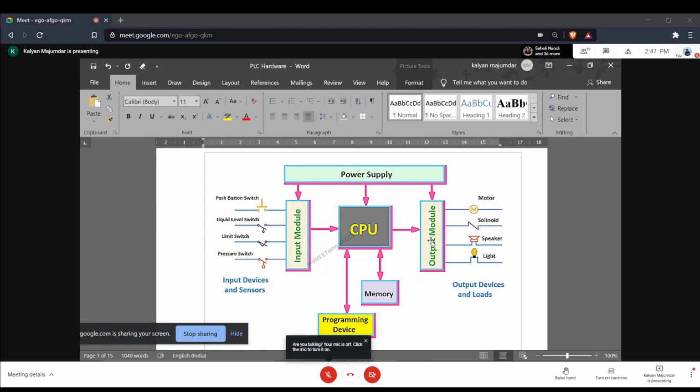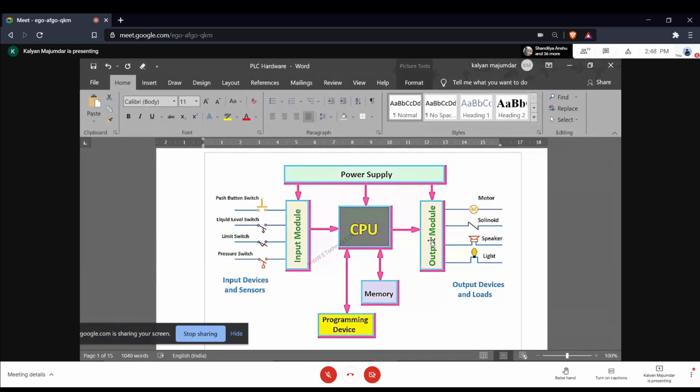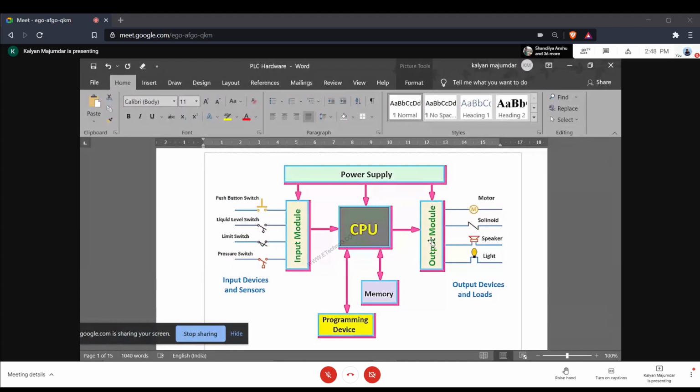So what is done is this programming device is connected to your PC and the execution is shown in real time. You can see all the contacts that are conducting or not, and what is the state of the outputs. So you can actually see your program running in real time, and then probably find out bugs and rectify them. So any PLC essentially needs a programming device, and how is the programming device connected?